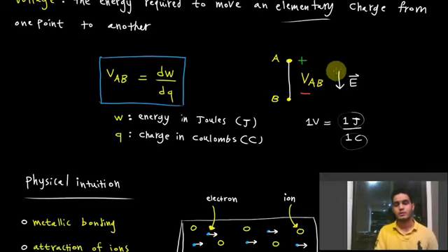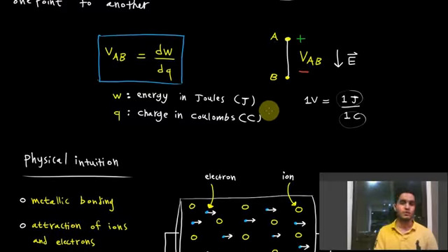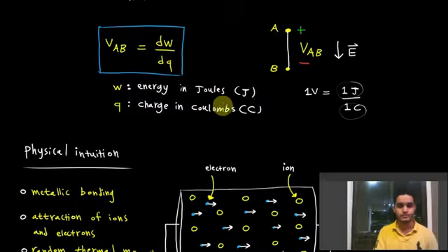Now, if the electric field, which corresponds to the voltage across any given device, is pointed in this case from top to bottom, the polarity would be plus minus, where the electric field emanates from the positive and goes to the minus sign. That's the convention for voltages. And as we discussed in the previous lecture, the convention for the current is to go from the positive to the negative. That is a conventional current, whereas the actual electrons flow from negative to positive.